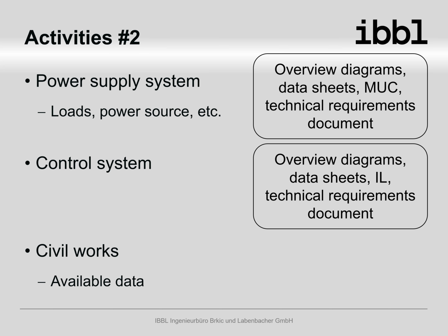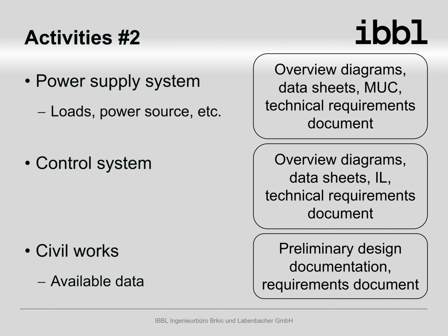The scope of basic civil design depends very much on necessary structures and available data. Typically, data for new plant to be built are available, but very important soil data are only partially available or assumed. Preliminary calculations and drawings for main buildings and foundations can provide information for quantity estimations and can be implemented in arrangement.